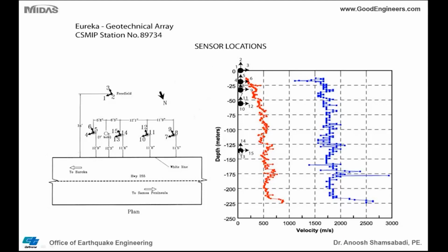Now, these are not the motion that is going to basically shake the structure directly. We feed these motions through nonlinear springs attached to the piles, and then we shake the bridge. And if you do a substructure, you need to come up with a kinematic motion, which is none of this motion. That means you really have to model the foundation separately using this motion and come up with a kinematic motion. But if you use a direct motion, no problem. Just attach this motion to the springs, and the structure will take, the finite element model will take care of the rest for you.